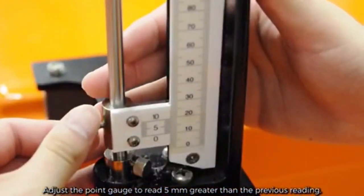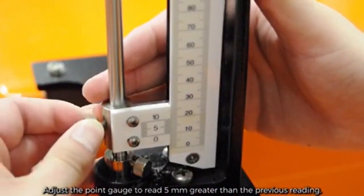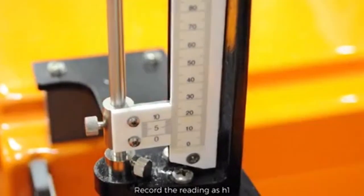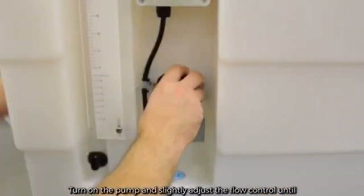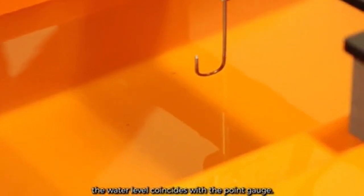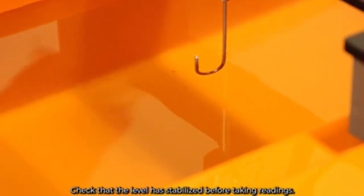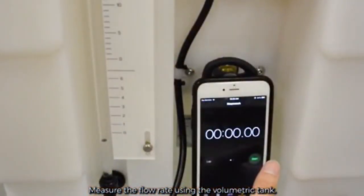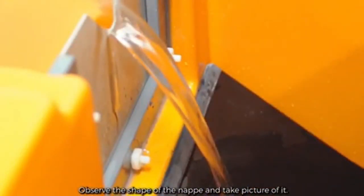Adjust the point gauge to read 5 mm greater than the previous reading. Record the reading as H. Turn on the pump and slightly adjust the flow control until the water level coincides with the point gauge. Check that the level has stabilized before taking readings. Measure the flow rate using the volumetric tank. Observe the shape of the nappe and take a picture of it.